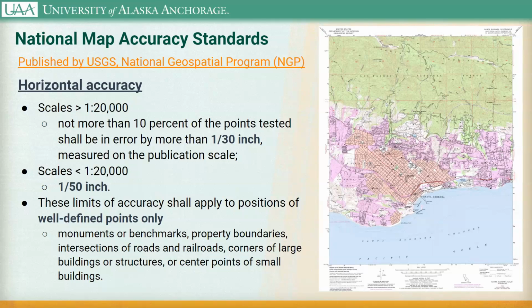Something might look perfectly accurate at a very zoomed out scale, and when you move in closely, you find that the little dot of where they put Juneau isn't actually in Juneau, it's nearby, but you're looking at the map on a different scale and it didn't matter at that scale. So understanding that accuracy standard and the relationship to scale is important if you need to define that sort of thing.